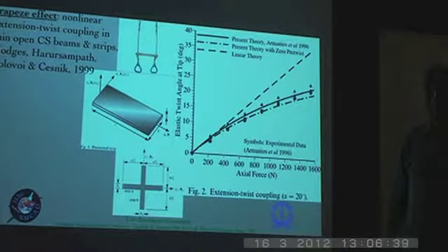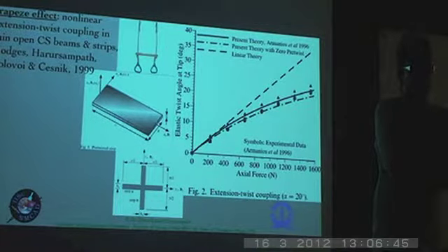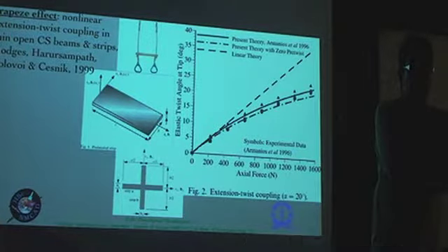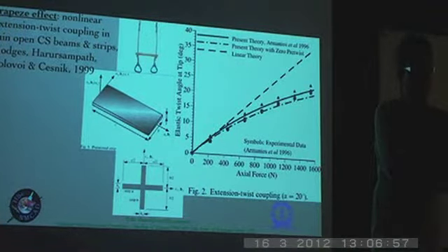Sir, in the sense you said this, because there is no axial load in the wing, this trapeze effect is not much important. When you consider a moment, because of the lift, there is a moment in this. And when you consider a cross section and look at the moment, the stresses developed on that cross section, on the top half it's compression and on the bottom half it's tension. Because of that there is an extension. Exactly. So then this becomes vital with pre-twisted. Sure. If that is also twisting, if there is a torque or it is twisting, then it becomes very critical. You're right.